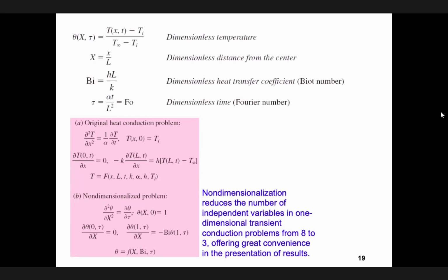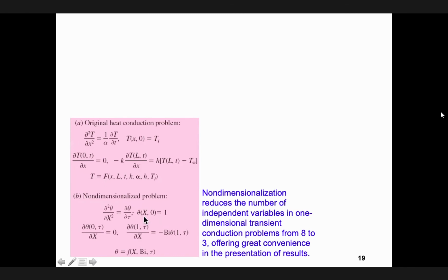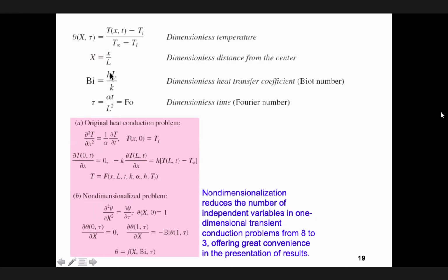Again, by non-dimensionalizing it here and here, you will see there is a new variable that comes out, and we call it the Fourier number. You had the Biot number before, you have seen it before. We non-dimensionalize it, we have this one, and by doing this you find another dimensionless number. This is also non-dimensional. You call it the Fourier number. Therefore, now you have the differential equation, and you're trying to solve it based on these boundary conditions. But by doing non-dimensionalization, you end up with 2 other dimensionless numbers.